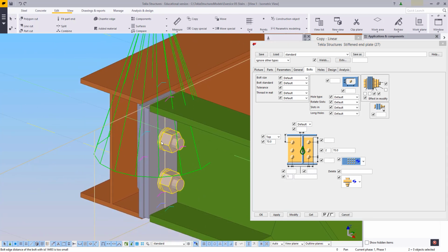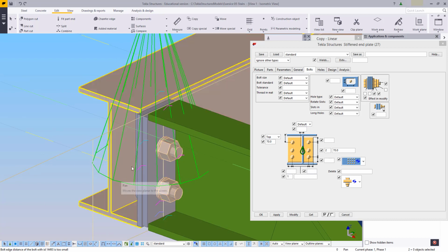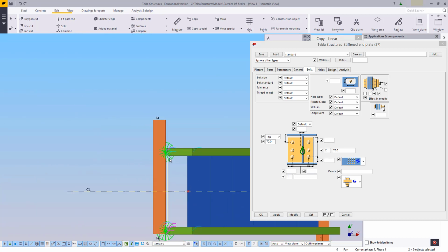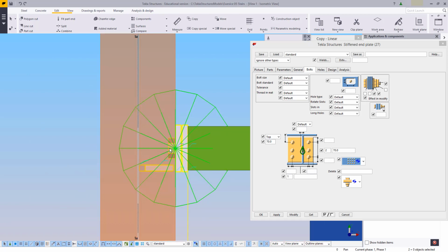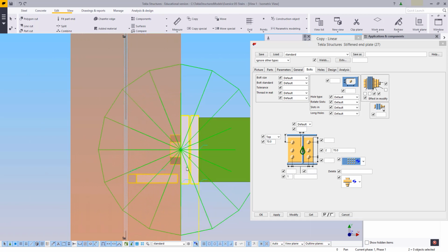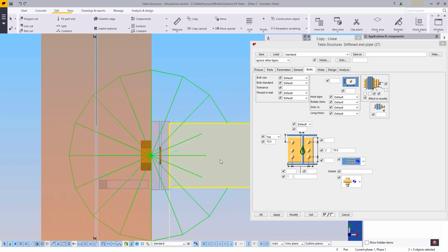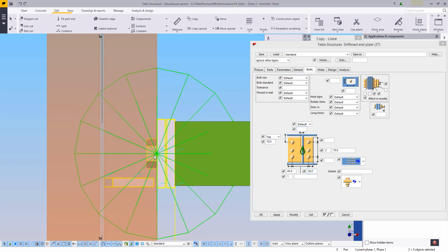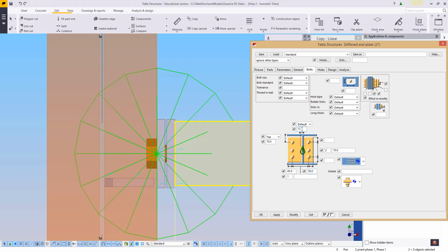Now, unfortunately, the bolt isn't right in the center, but it's a little bit off center. So let's get a nice top view, open this up, and have a look at our settings. One side will be 45, the other side will be 30, as they show in the connection detail. But our connection cannot be centered. It's going to move about 7.5. Currently it's right in the middle.